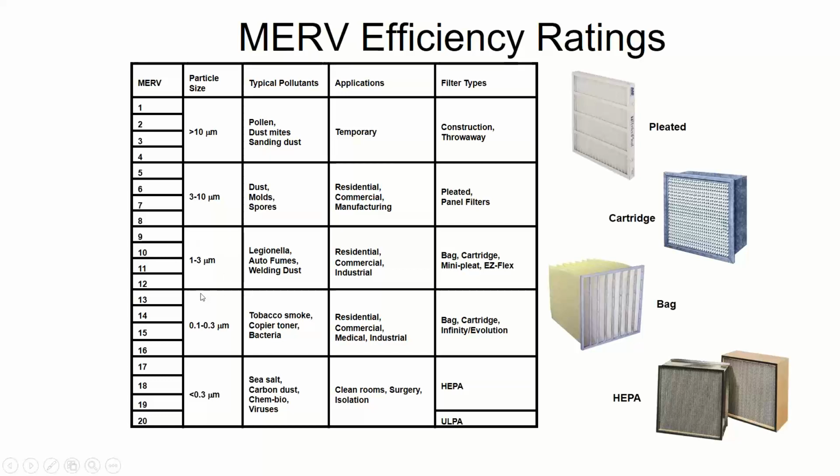I don't know anybody who makes a Merv 12, but there's Merv 10s and 11s out there. I know Honeywell has a Merv 11. That would probably be a pretty good spot. You can certainly go better than that, and there's reasons to go better. But you probably only need like a Merv 8 to catch most of the pollen-related stuff.